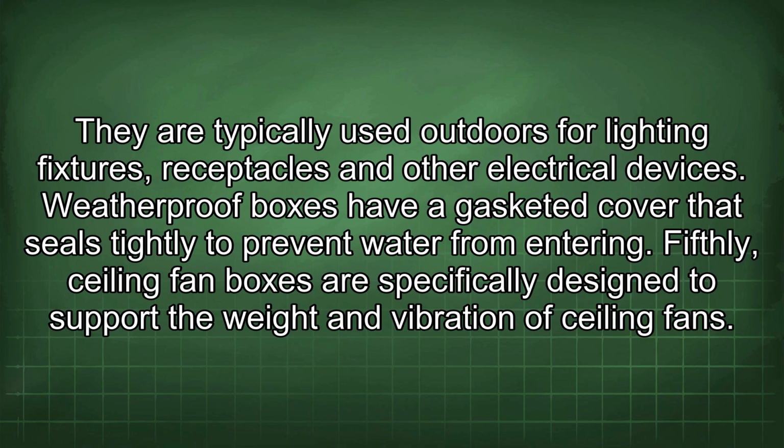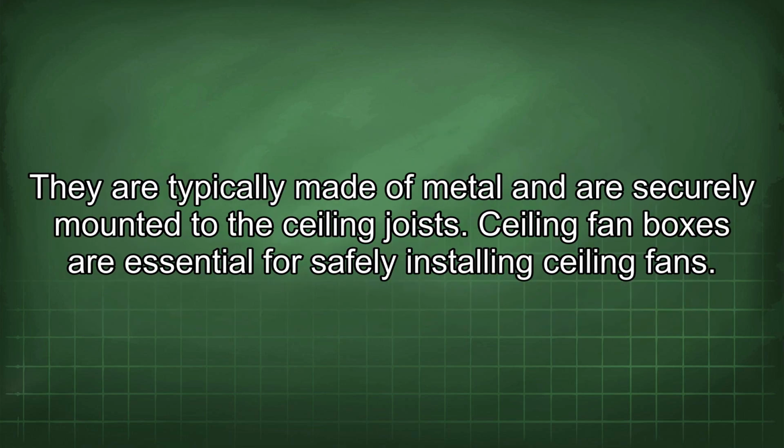Fifthly, ceiling fan boxes are specifically designed to support the weight and vibration of ceiling fans. They are typically made of metal and are securely mounted to the ceiling joists. Ceiling fan boxes are essential for safely installing ceiling fans.